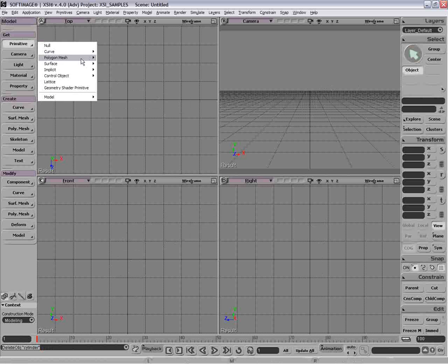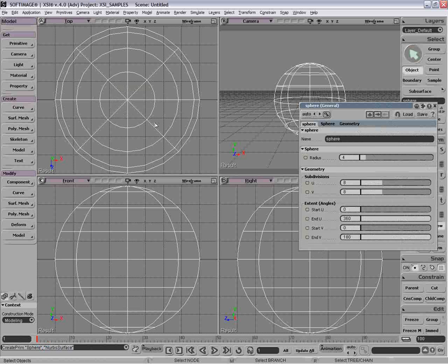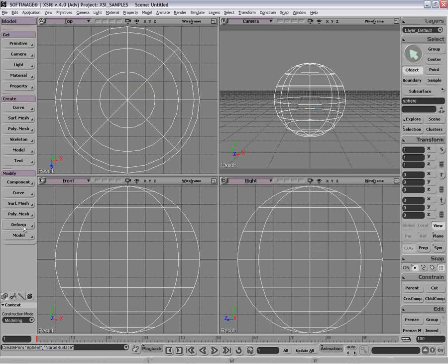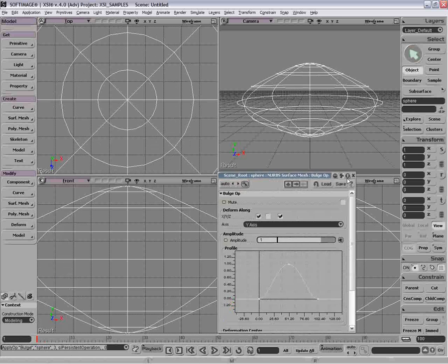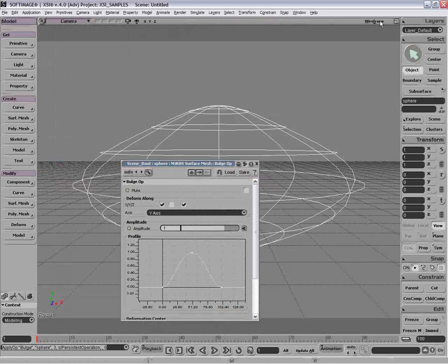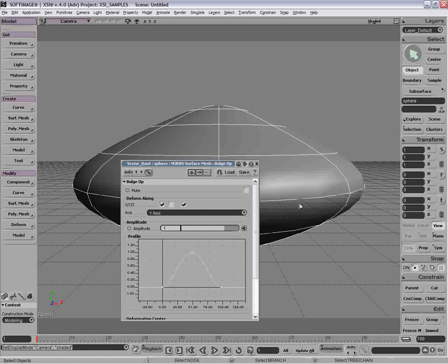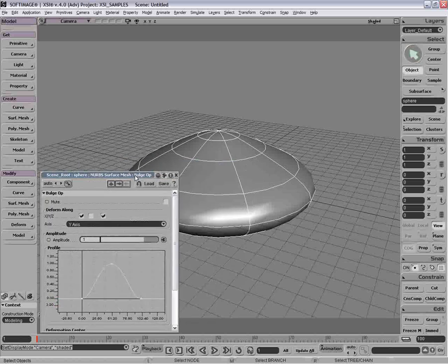Okay, the next thing I want to talk about is these deformers. Not all of them, but a lot of them have a place for a weight map. Basically, anywhere where there's an amplitude or something like that, you can connect a weight map, and that's a very important part of working with it. So let's take, for example, a bulge operator. Now, a bulge operator you see has this amplitude, and you have this little plug icon right here. And whenever you have that plug icon, that means you can attach a weight map to control where this deformer is going to be taking place.